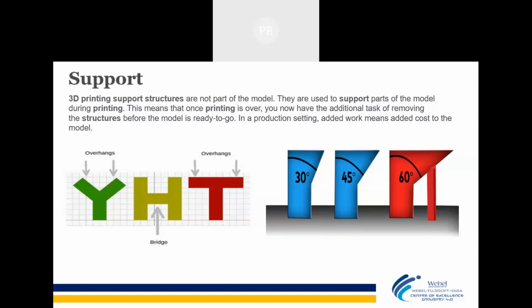For example, 3D printing is a layer by layer technology, right everybody? My Y is in a standing position, in a vertical position, like it is now here. You're seeing the Y? Yes, sir. This part has a base. This is the bottom part, which has a base. Material can be deposited up here. Then it will go like this, like this. But at this corner point, there is no base up here. How will the material deposit here? So it will develop an artificial support from this part and this part.